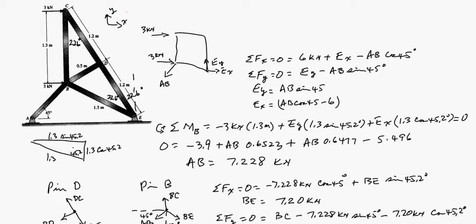Now on this truss, notice we can draw the entire truss. We're going to work again in the standard XY coordinate system. We can draw the whole truss. Notice that AB is a two-force member, so we can show it acting at point B as a two-force member at 45 degrees. And take the entire thing. Here it is pinned to the world at E.